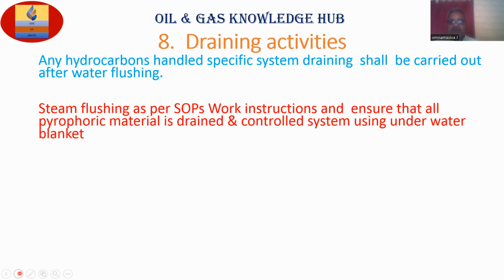Flushing, as I told you previously, is water flushing first. There will be SOPs for every flushing. Water flushing, steam flushing, specific SOPs are there. These SOPs you have to read, understand, and execute. So, all pyrophoric material is drained. What is this pyrophoric material?